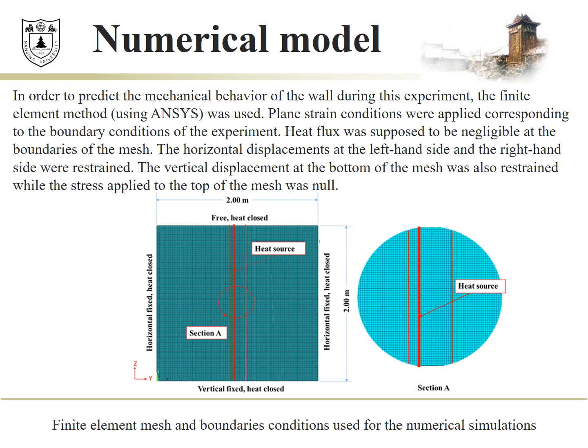The constitutive laws used in this study are summarized as follows. First, only conduction is considered for heat transfer. Second, the mechanical behavior of the wall is linear elastic, while that of the soil is elastoplastic, with the Drucker-Prager yield criterion. Third, the thermal behavior of the wall and the soil is linear elastic.